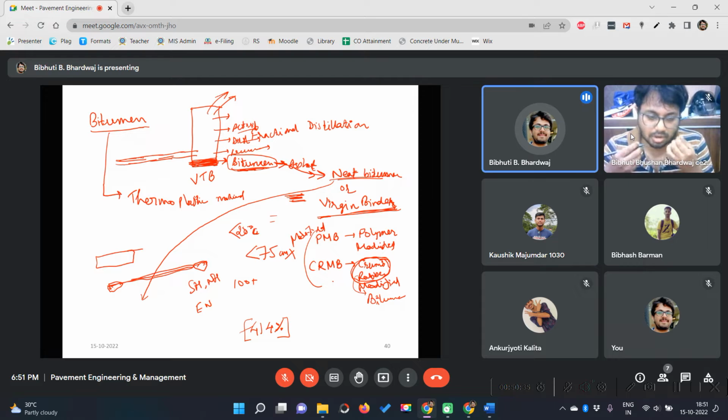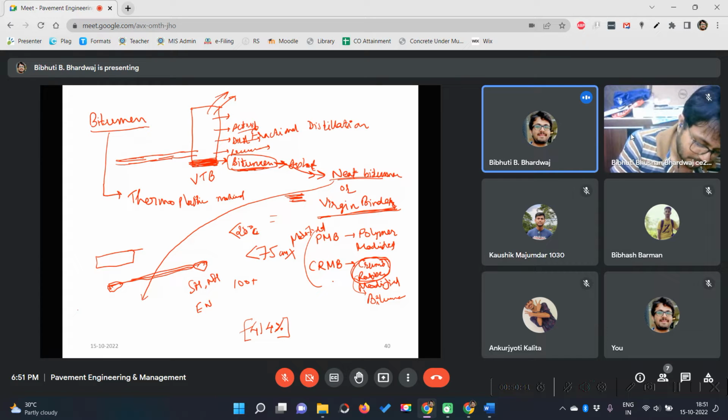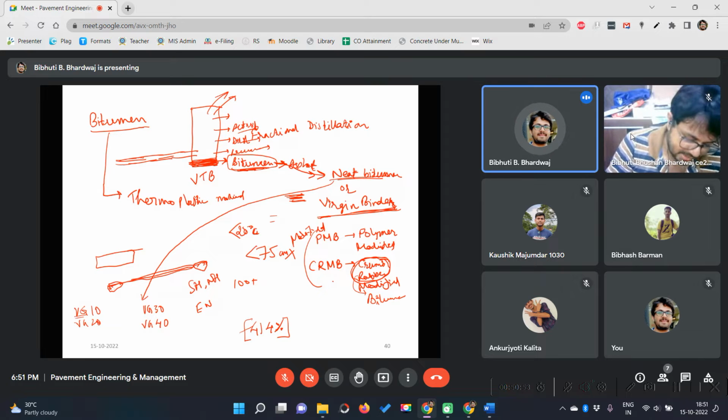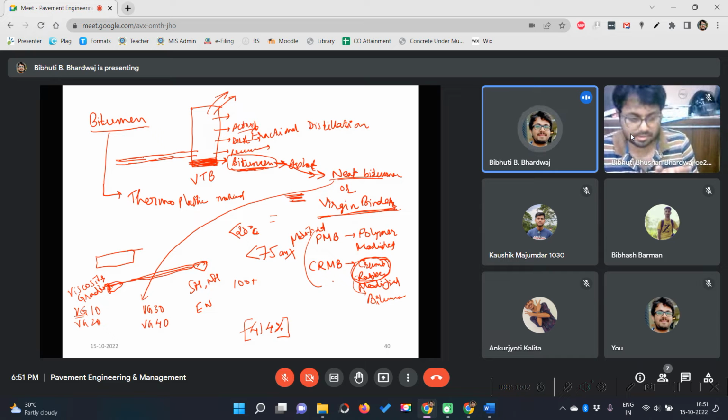So based on how viscous the bitumen is, it is classified into four categories: VG10, VG20, VG30, and VG40. So what is this VG? V for viscosity and G for grade. Viscosity grade 10, viscosity grade 20, 30, 40.